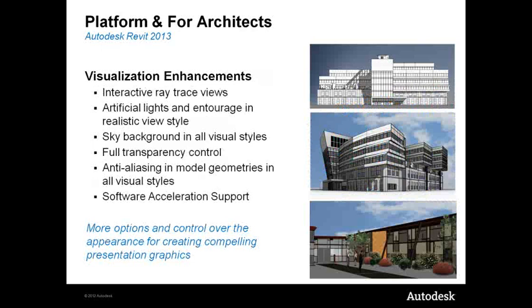Visualization enhancements present you with more flexible visual styles combinations, helping to add value to visualization techniques and improve the interactive experience. There is a new interactive ray trace view. It provides a more realistic view of the model, including shadows, materials, reflections, lighting, and entourage without fully rendering the view. This new mode of display is added to the current list of display styles.